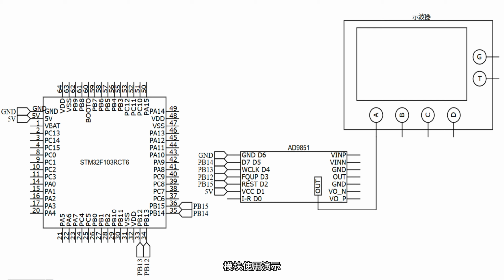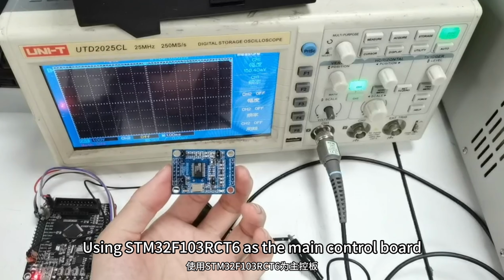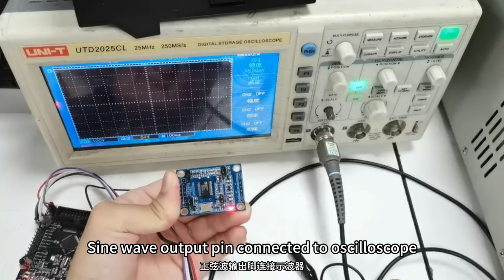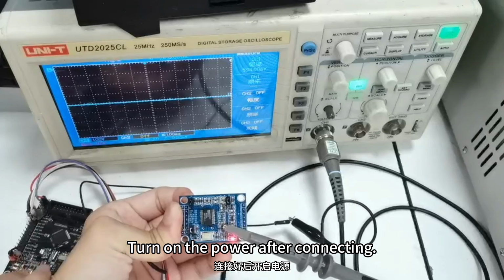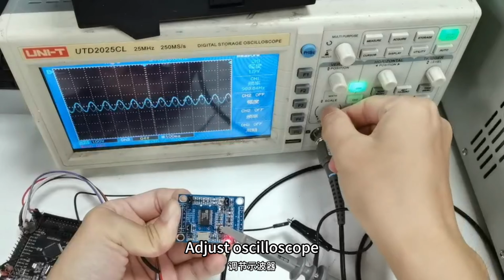Module usage demo. The connection is shown in the figure. Using STM32F103 or CT6 as the main control board. Connect the modules via the serial interface. The sine wave output pin is connected to the oscilloscope. Turn on the power after connecting. Reset the motherboard. Adjust the oscilloscope.